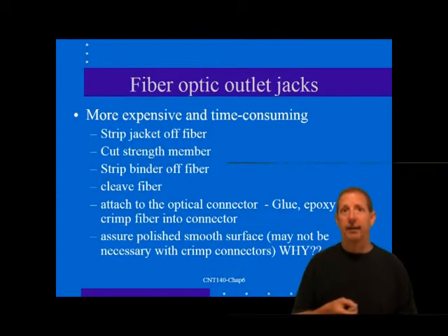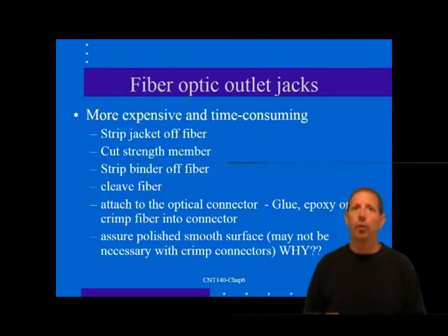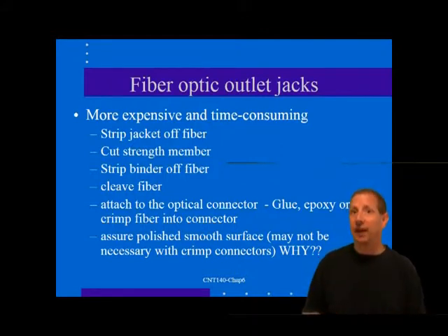Fiber optic outlet jacks. The fiber optic technology has become so important that we've devoted an entire chapter to it when we get to Chapter 11. The outlet jacks for fiber optic connections have several unique requirements. The fiber optic outlet must allow the station cable fibers to be terminated and connected into a jack plate. In addition, the design of the jack plate must allow the easy attachment of an optical jumper to the workstation equipment. A special passive coupling device called an adapter is used to connect the two fiber optic cables at the outlet jack.